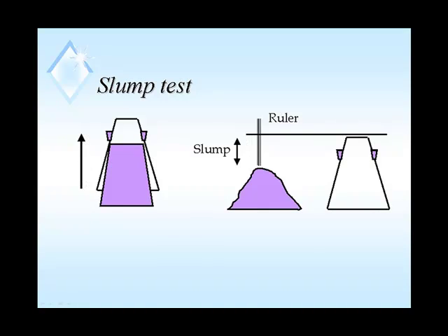The slump test is a very important tool in controlling the amount of water that you add at the job site. You really can't look at concrete by eye. Even after years of doing it, it's a very poor gauge of whether or not there's enough water, whether or not it's workable enough. So a slump test is used, the sample is taken, and you make a controlled measurement of the workability of the concrete. And I have a video showing that process.